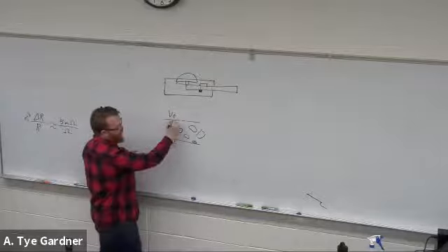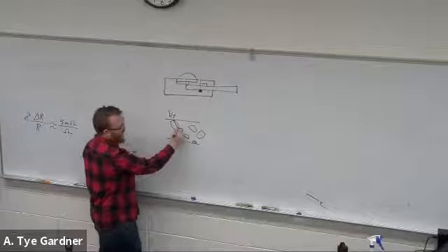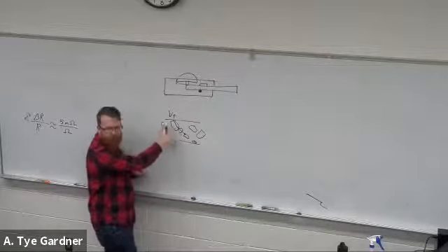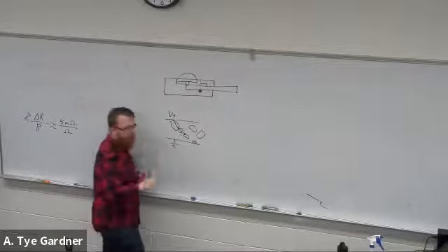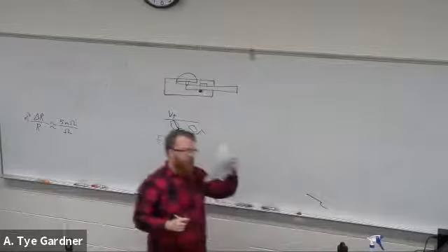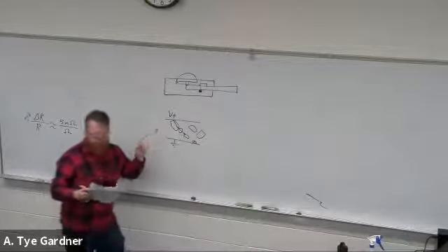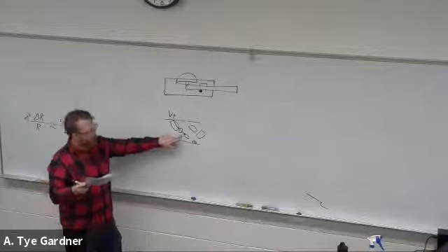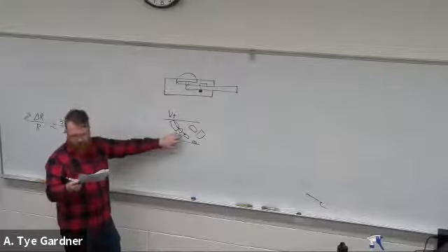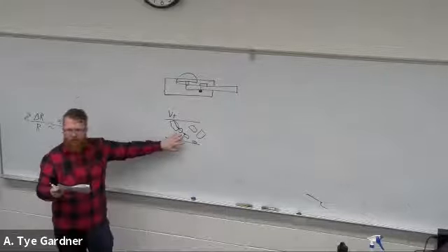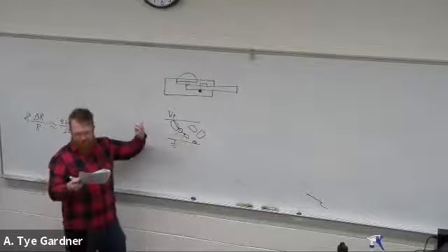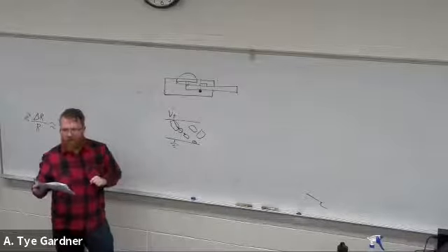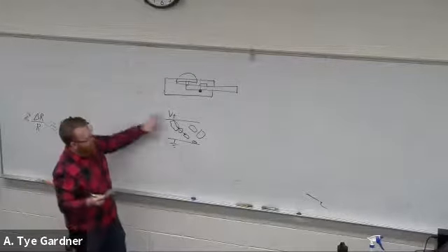Well, the current can jump little bits through diffusion. So like this is just traditional flow because these two globs are connected together. Specifically, it is called just conduction, right? Then if they're close, but not too close, you're going to have hopping is what they call the phenomenon. And then lastly, if you're super close but not quite there, they call it tunneling. And I don't think I'm going to test on those, but it's just kind of an interesting effect.